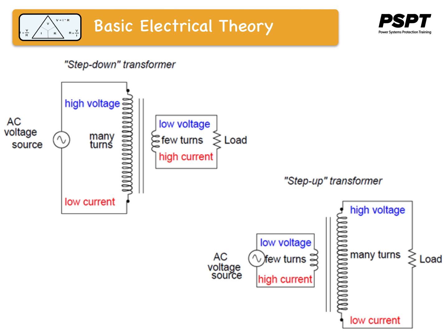The transformer's ability to step AC voltage up or down with ease gives AC an advantage unmatched by DC in the realm of power distribution. When transmitting electrical power over long distances, it's far more efficient to step the voltage up and then step it down at the end. The advantage here is you can use smaller diameter wire with less resistive power loss in the transmission process.